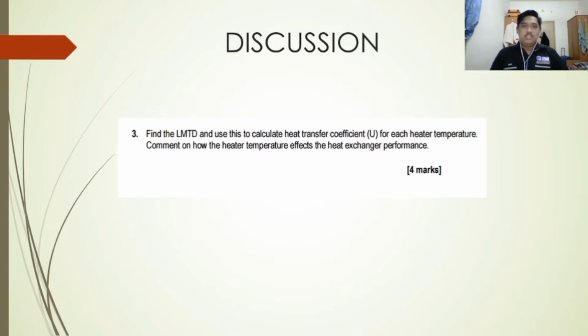For discussion number 3, we need to find the LMTD and use this to calculate the heat transfer coefficient, which is U, for each heater temperature. Then, we need to comment on how the heater temperature affects the heat exchanger performance.